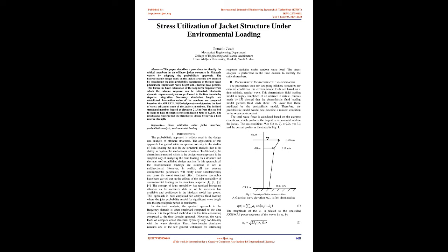In structural analysis, the spectral approach in the frequency domain is often employed compared to the time domain. It is the preferred method as it is less time-consuming compared to the time domain approach. However, the wave loads on complex ocean structures typically vary nonlinearly with the wave elevation. Thus, time domain simulation remains one of the few general techniques for estimating response statistics under random wave load. The stress analysis is performed in the time domain to identify the critical members.